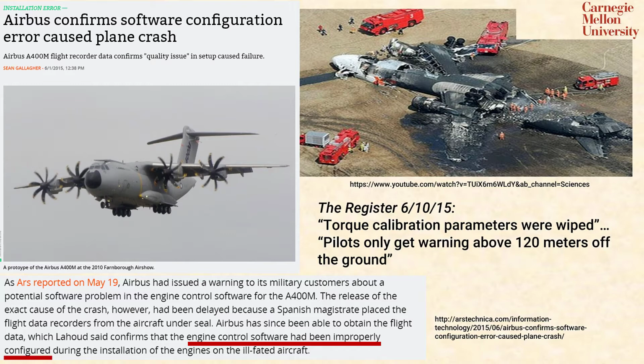So that means the aircraft took off with bad configuration, got up in the air, and then lost 3 out of 4 engines. The pilots attempted to land but were unable to do so successfully, resulting in a crash that killed 4 out of 6 crew members. Afterwards, someone associated with this said they never imagined they'd lose 3 out of 4 engines. But a bad configuration can be a common cause failure that causes multiple redundant systems to all fail together.